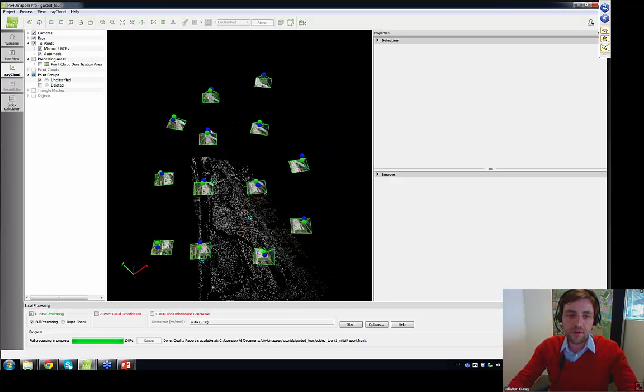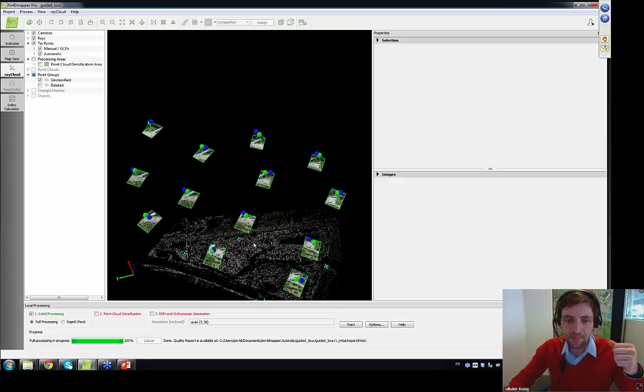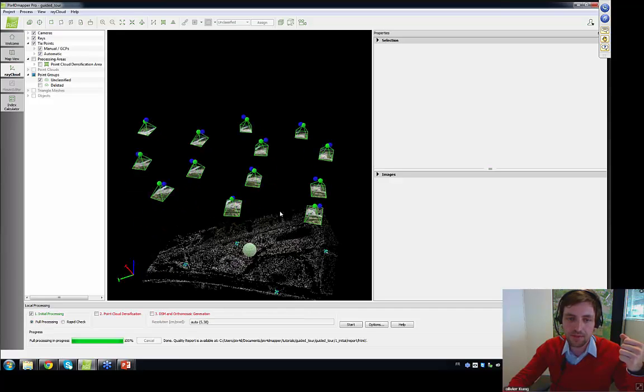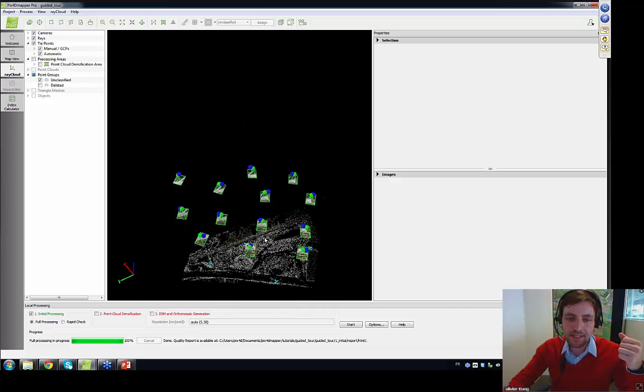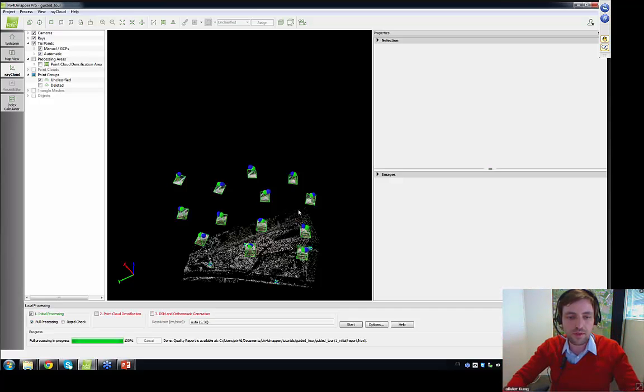If you don't see a pattern and the errors are sometimes to the right, sometimes to the left, and so on, that basically means that what you see there is very likely just the error of the GPS. And if it's very close by, it's just the 1 to 2 meter error of the GPS. However, if you see a systematic pattern, like everything misaligned, or the arrows between the blue and the green being much longer, that usually indicates quite serious issues with either the GPS or the calibration.